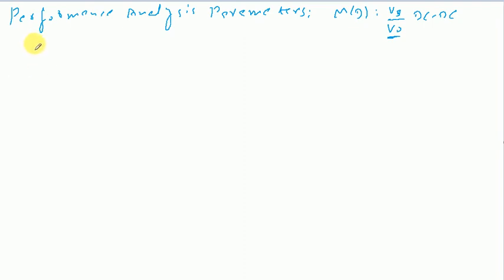This is important because we'll have different types of circuits and a few of them will be doing the same job. So this will help us establish the difference between different types of converter circuits. For example, if I'm saying that a half-wave rectifier circuit converts an AC voltage into DC, then a full wave rectifier circuit also does the same job, and then even a three-phase rectifier circuit.